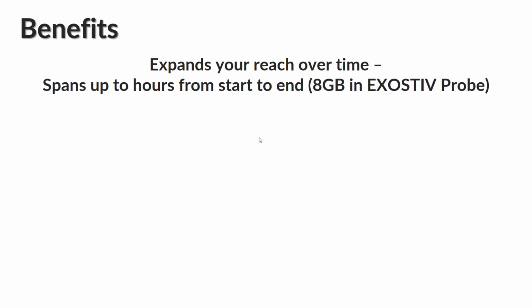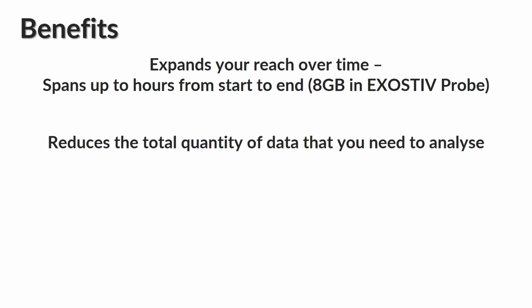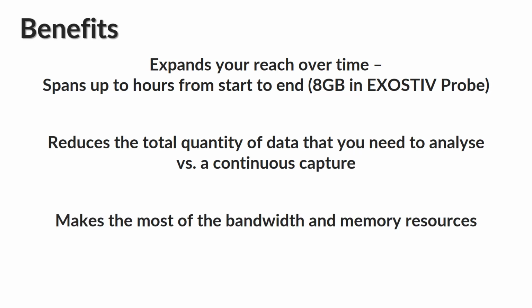Using interrupted captures with Exostiv has many benefits. First, it increases your reach over the FPGA in operation. With the 8 GB buffer provided in Exostiv probe, your capture can span over hours. Second, if you concentrate on areas of interest of the FPGA timeline, you can reduce the total quantity of data that you need to analyze compared to a continuous capture. And finally, this approach will help you make the most of the bandwidth and the memory resources provided by Exostiv.